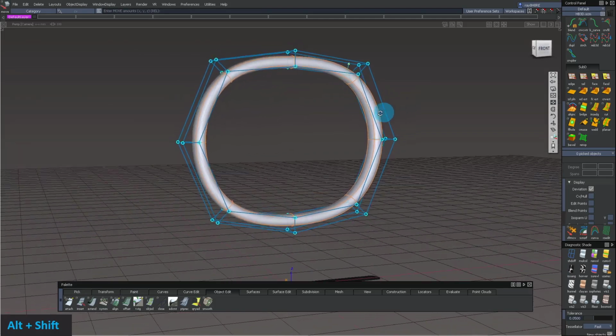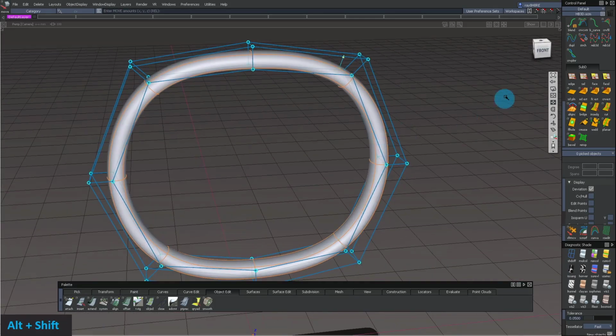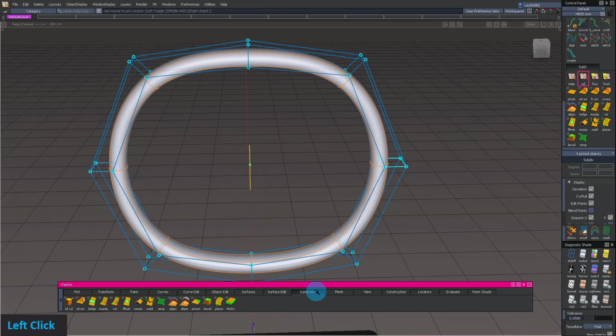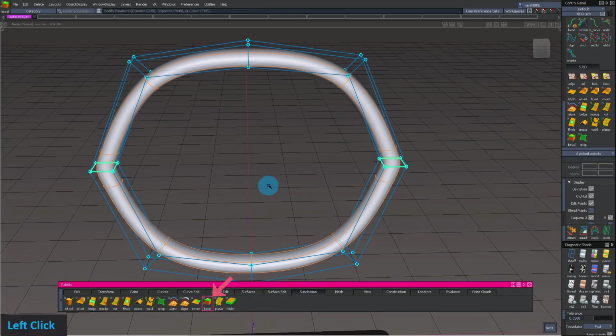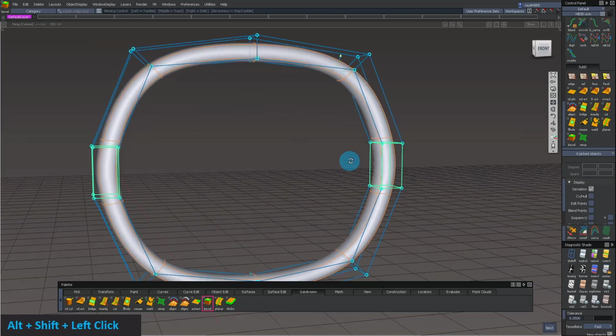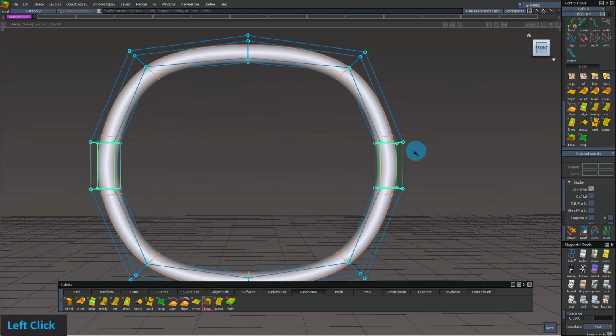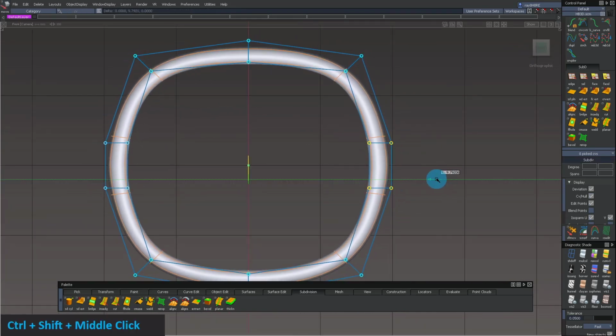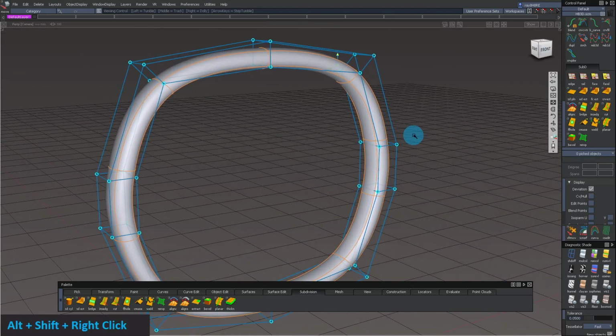So the first thing I'm going to do is bevel the edge of the steering wheel. So first I'm going to select that edge loop, and then I'm going to find the bevel tool under subdivision and then bevel. And that's an extremely powerful tool, and I think a lot of you already know those concepts. So you do that, and then it gives us another set of faces in between them, right? And I'm going to try to see what thickness I want.